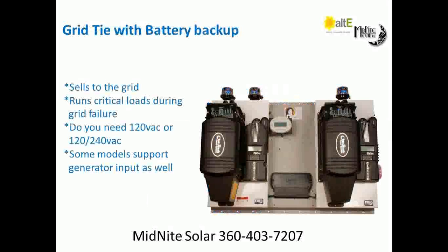Again, it sells to the grid. It will run critical loads during a grid failure, whereas a pure grid tie system will not. A couple of questions you need to know: do you need 120 or do you need 120/240? And some models of grid tie inverters support generator input as well as utility input.